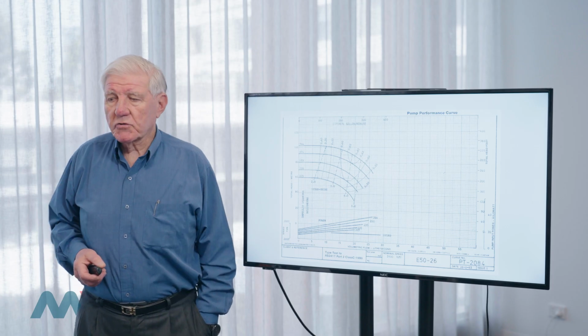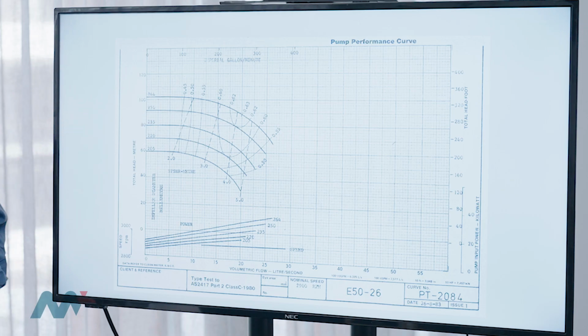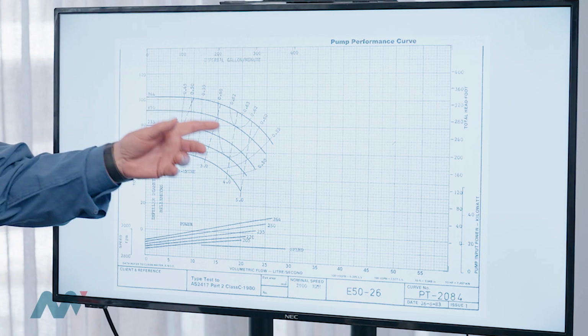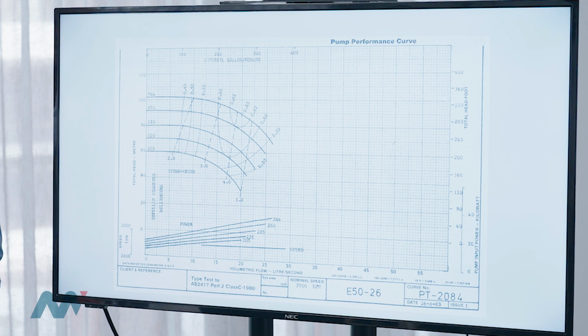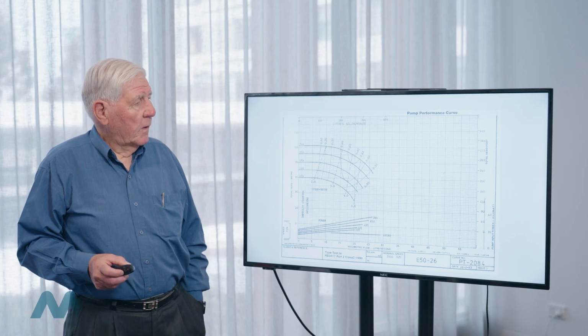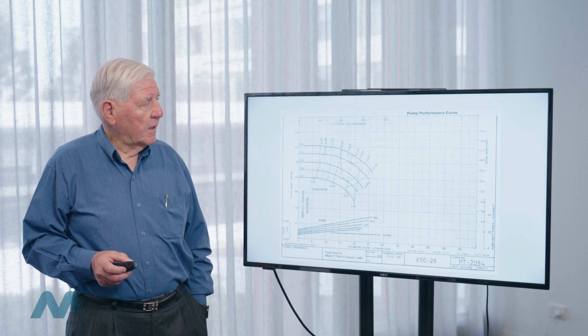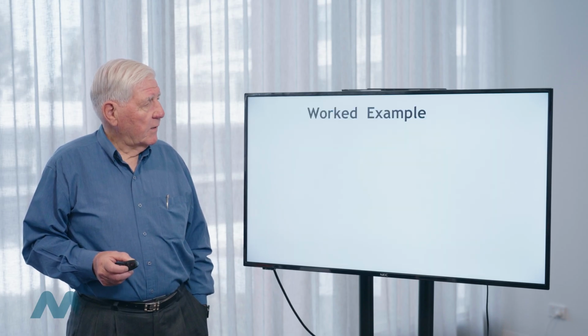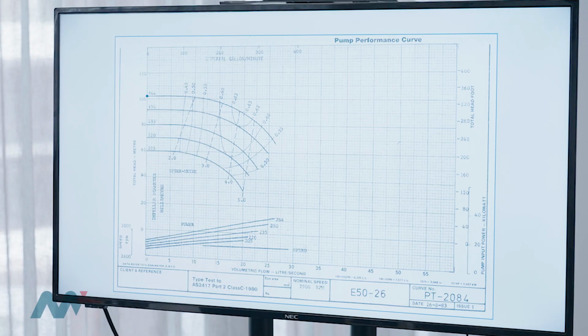Let's see how we construct that curve. So here is the pump curve, and we're going to look at the maximum diameter. This is the single pump operation. It's got a best efficiency point of just over 20 litres a second. What we're going to do now is to double the flow at uniform heads. So our starting point is zero flow. At zero flow, the pump should be producing equal head with each pump.